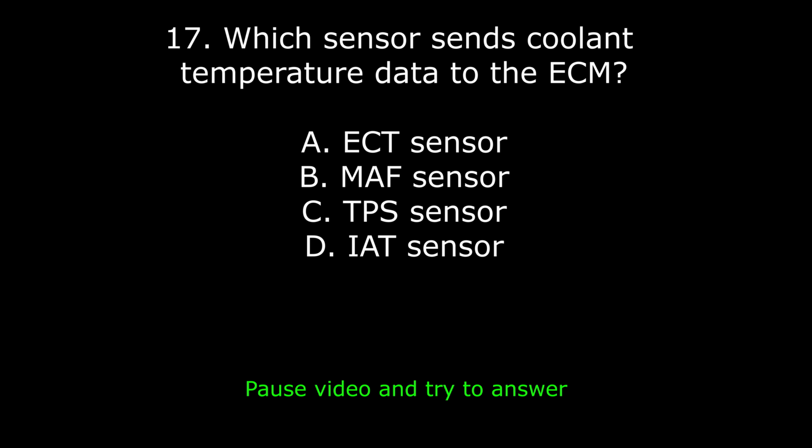24. A squealing noise occurs immediately after starting a cold engine. Likely cause: A. Loose drive belt. B. Bad water pump. C. Dirty battery terminals. D. Air in cooling system. Answer: A. Loose drive belt. Explanation: cold weather stiffens belts and loose tension causes slippage and squeal.